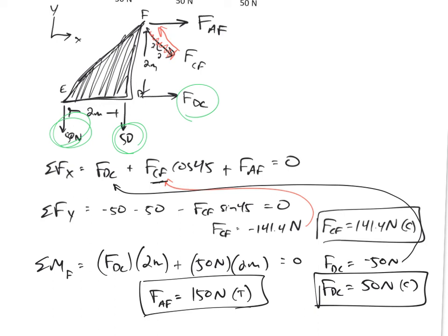And also remember, for that problem, if your answer comes out negative, I want you to make it positive and go back and redraw it on your free body diagram. Make sure your free body diagrams are self-sufficient. Make sure you include all dimensions, angles. Make sure you draw your X and Y axes.